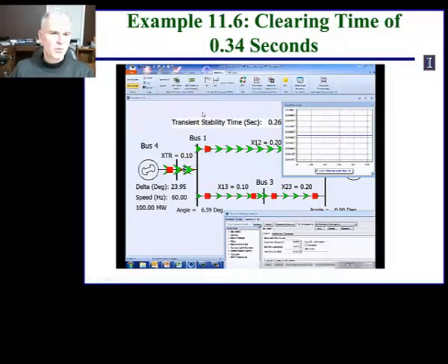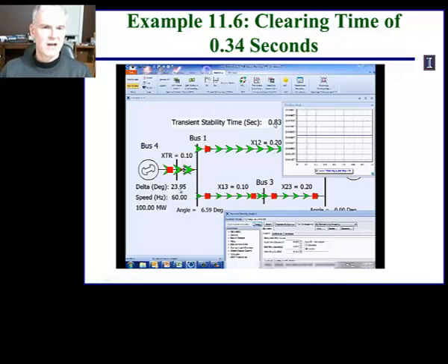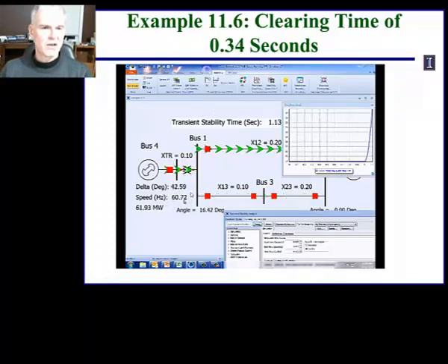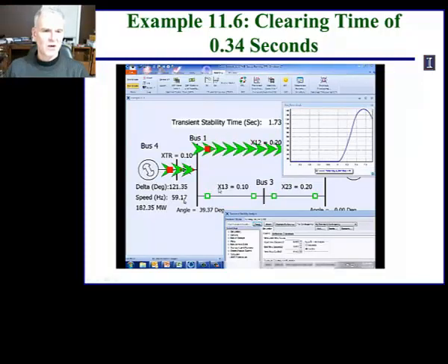That shows the rotor angle on bus 4, and at the bottom there is time. You can also see right here, time is going forward. At time t equals 1, we apply the fault, the rotor angle starts to accelerate, we clear the fault, and then we have our system oscillating around here.